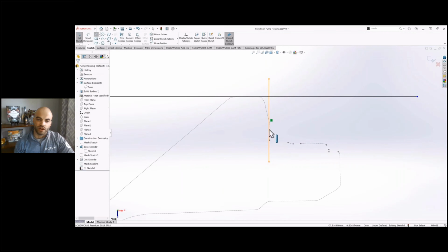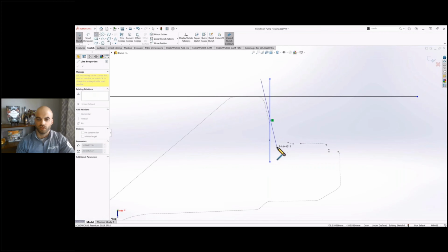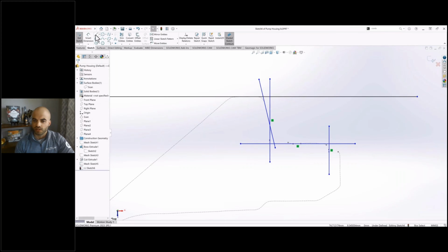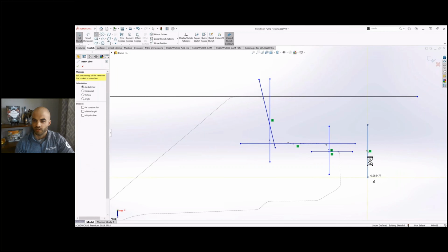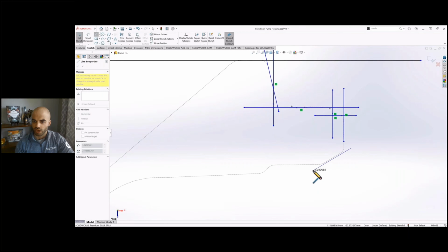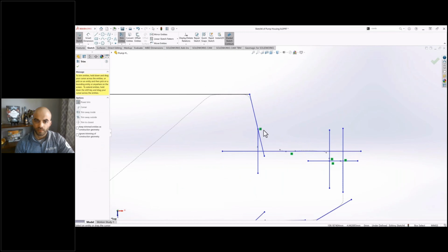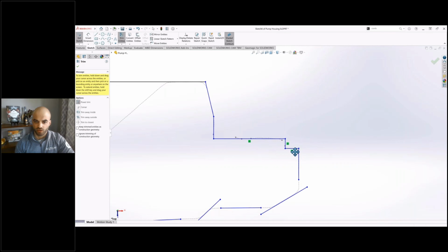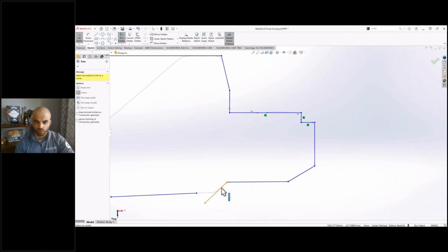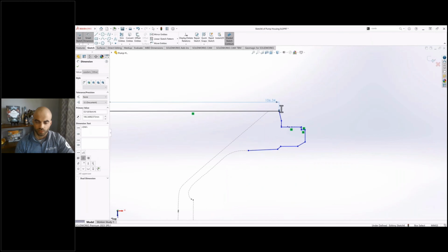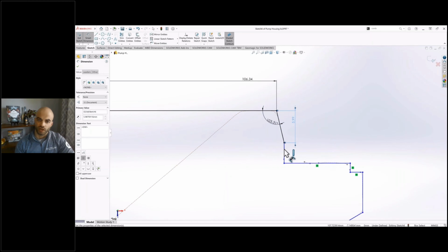What I was building there is we're actually going to do this as a single revolve. You could argue that it is 2 different features. We're going to do it as a single revolve here and connect it in the middle with that little dummy piece of geometry at 10 millimeters that I had just thrown out in the middle. That's going to go away when we do a boolean operation at the end with all these bodies. So you can see here I have all my crazy sketch going on, and then I'm coming through and doing power trimming and corner trimming in order to get my final geometry here.